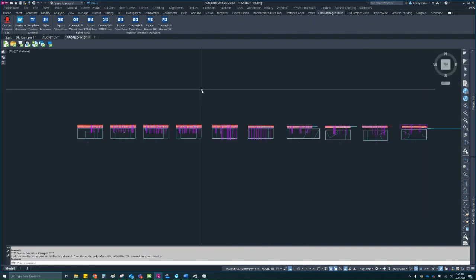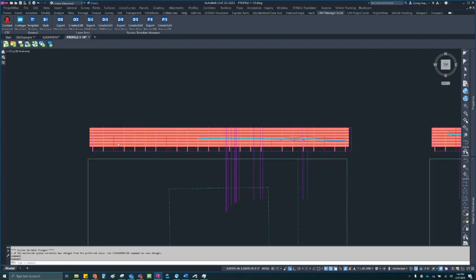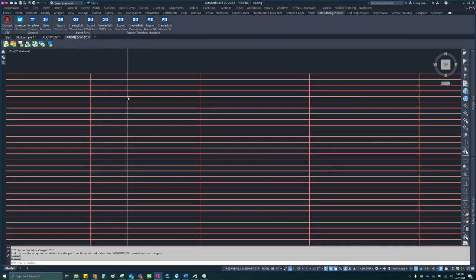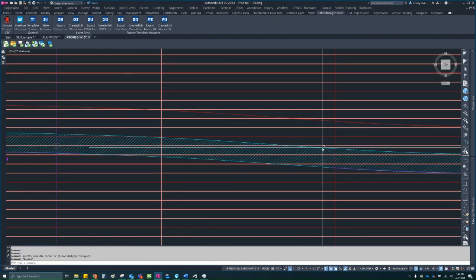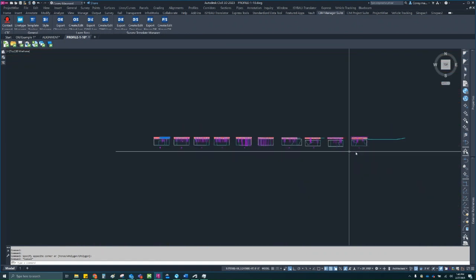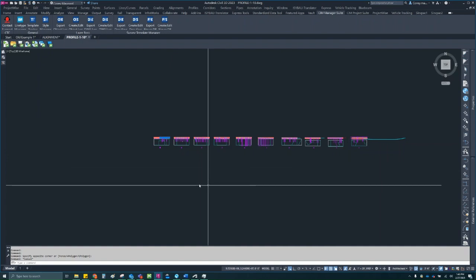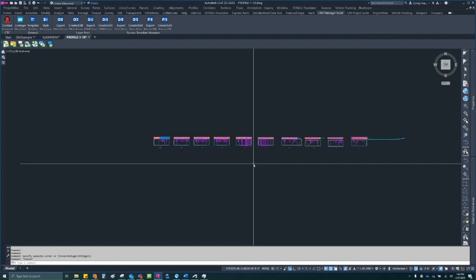Similarly, in the profiles, that drawing is utilized to create the plan view with the survey XREF, and then similarly, this is where the profile views are created, and it's just lines that someone drew. The profile itself, just lines. None of these are geospatially referenced. In other words, the coordinates are not relevant. They're just based off of 0,0. However, this does seem to be the current industry standard.